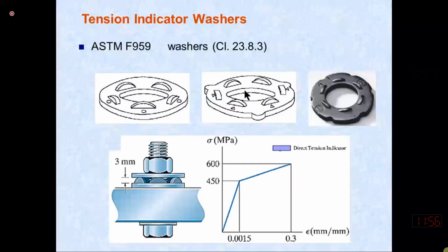So what does this mean? I am providing the strain, which is a function of the deformation and the length of the grip. And I know the E value of the steel. So indirectly, I want to determine how much deformation I need to provide in the bolt to produce some pre-tensioning. Because when I am reducing these thicknesses, the bolt tends to stretch. This bolt tends to stretch.